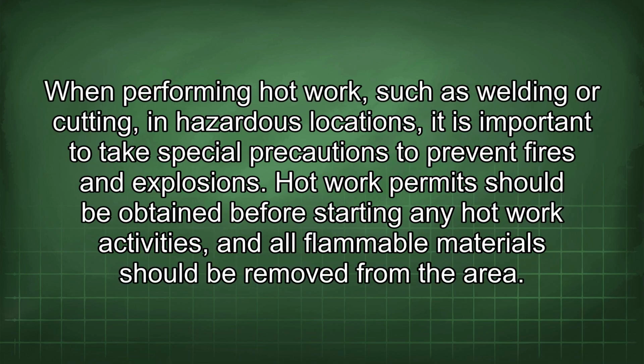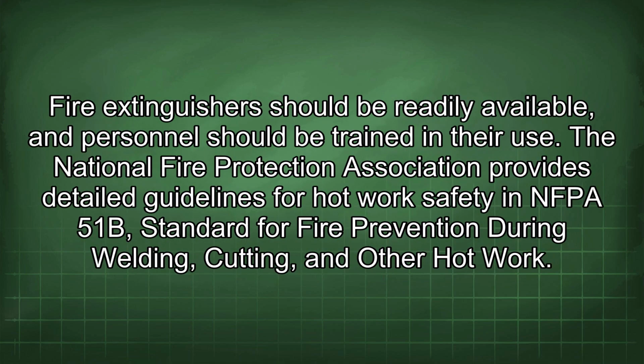When performing hot work, such as welding or cutting, in hazardous locations, it is important to take special precautions to prevent fires and explosions. Hot work permits should be obtained before starting any hot work activities, and all flammable material should be removed from the area. Fire extinguishers should be readily available, and personnel should be trained in their use. The National Fire Protection Association provides detailed guidelines for hot work safety in NFPA 51B, standard for fire prevention during welding, cutting, and other hot work.